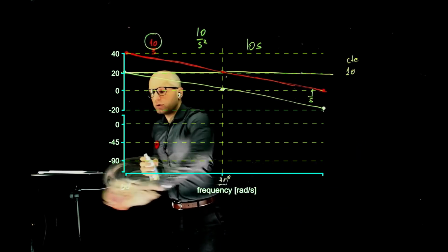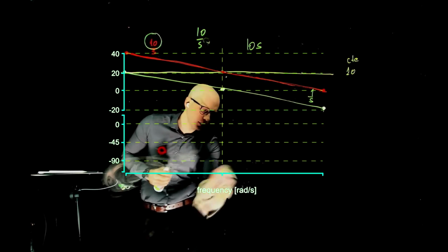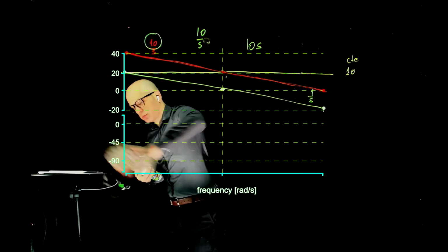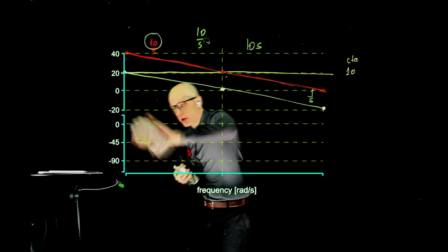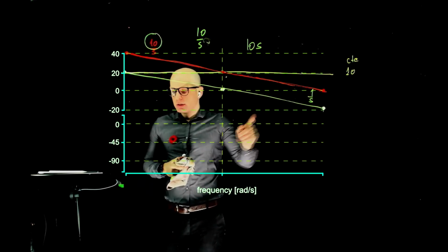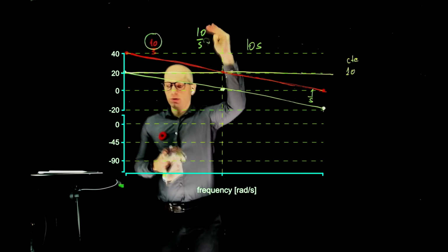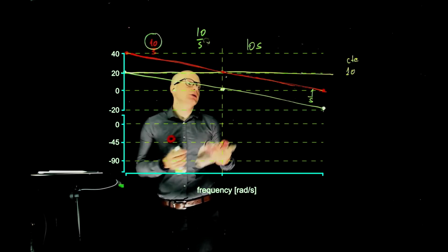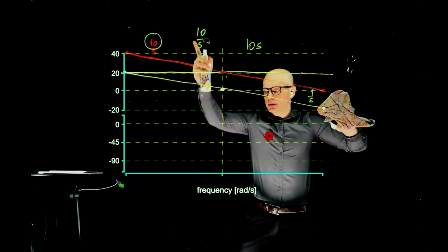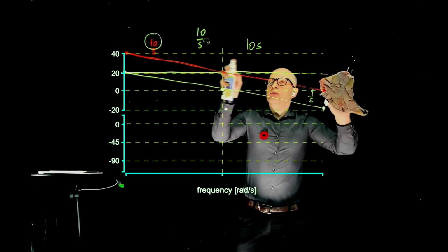And what happens if this was, let's say, 100 over s? The upward shift would just be greater. The upward shift would be 20 log of 100, which is the same as 20 log of 10 squared. The 2 comes to the front. That's 40 log of 10. That's 40. So everything would shift up by an additional 20 decibels. It's already shifted up by 20. Multiply this by 2, it's another 20. Moving everything up.